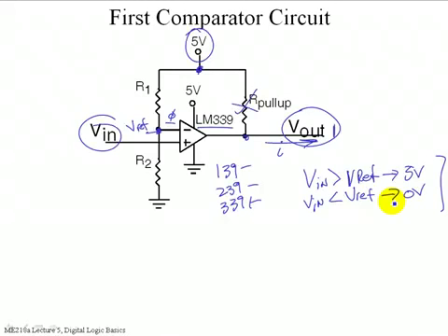Wouldn't it just have problems sourcing current? Well, you have to source even at least a little bit of current to measure a voltage, because we don't have any perfect measurement instruments, so it's going to have to source a little bit of current. But there's no way, there's no path for it to source current. And so what you're going to get is, what's the ambient noise that's being coupled into your voltage probe? Sometimes it reads high, sometimes it reads low.